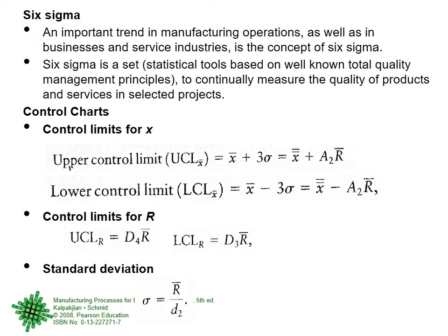But this is unbelievable, that rather than trying to think by some other experience and this and that what should be the tolerance limits, you decide based on actual math and science, statistics, that do sampling, take many samples. The more samples you do, the better the result. You have the mean value, which is of course the design value. This should be the diameter, and plus minus some tolerance. So plus 3 sigma, minus 3 sigma. You put these tolerances and then you will. We will not go into the details of all of that, but that is why it is called the Six Sigma approach in production and quality control and so on.